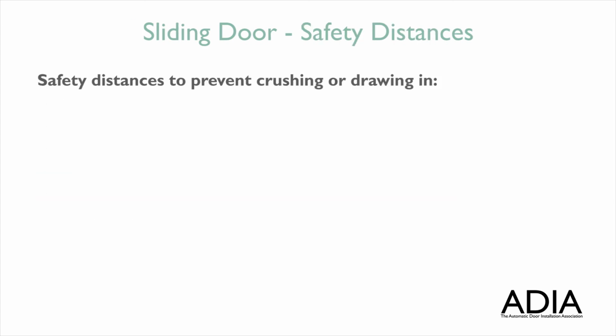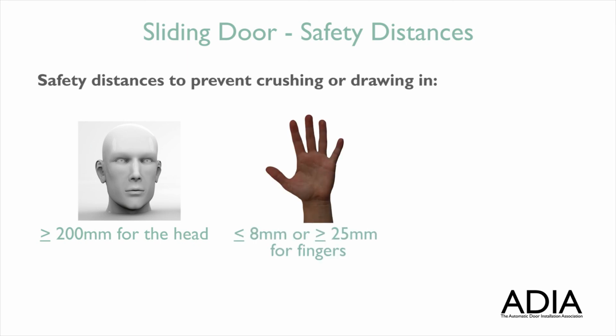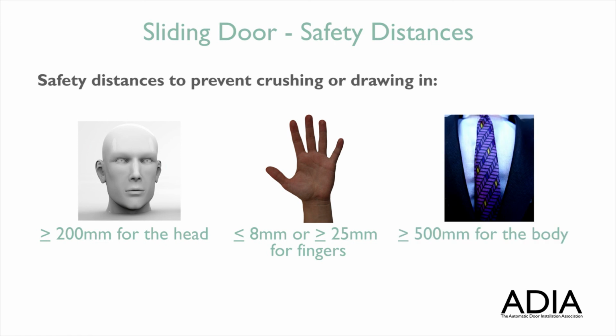Safety distances to prevent crushing or drawing in: more than 200 mm for the head, less than 8 mm or more than 25 mm for fingers, more than 500 mm for the body.